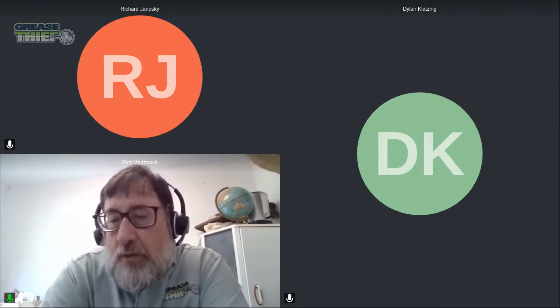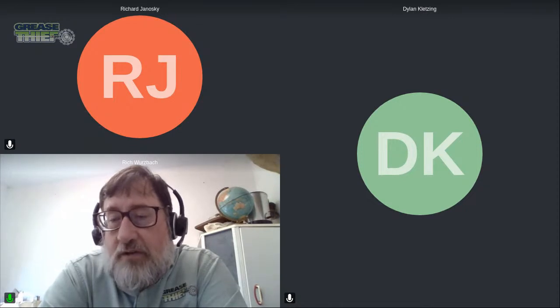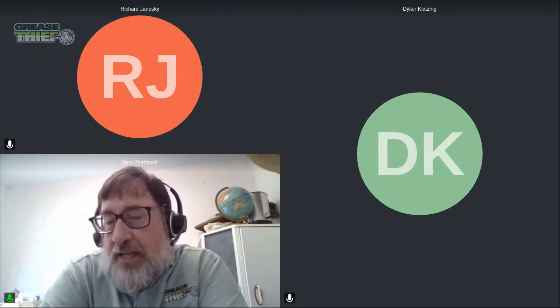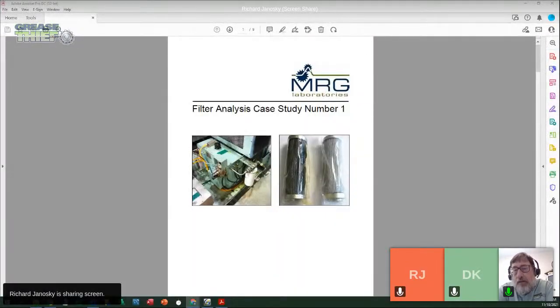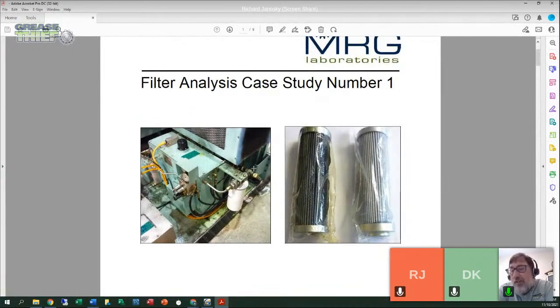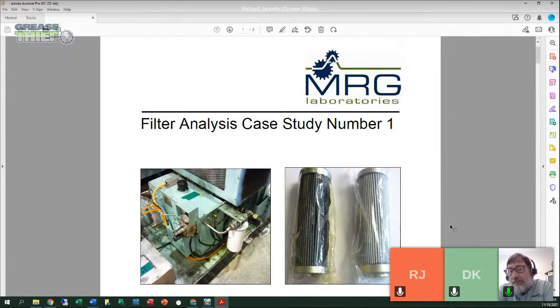And we've talked about that. We have similar kits for bearing analysis, root cause failure analysis for bearings. It's the same sort of thing where the kit comes back, the component is recovered, and the analysis is done. Then the next step is to rebuild the kit: identify the aspects that were consumed and cannot be reused, clean the ones that can, and then restock the kit and have it ready to go again. So thank you, Mindy, for that question.